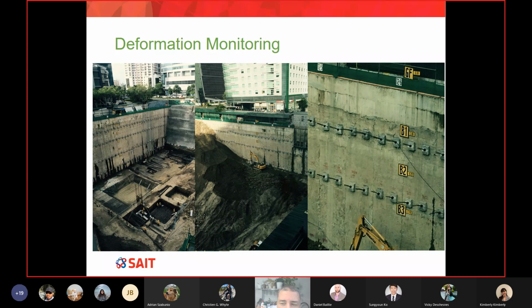So I'm asking you, if we're not able to precisely put our prism at the same location, this error can give me a false indication of the movement of the wall without the wall even moving. Or maybe I'm lucky, I put the prism and I got zero difference, while the wall is already in motion. So hopefully you understand the paper prism, because of their price and the way they are designed, is best for this application.